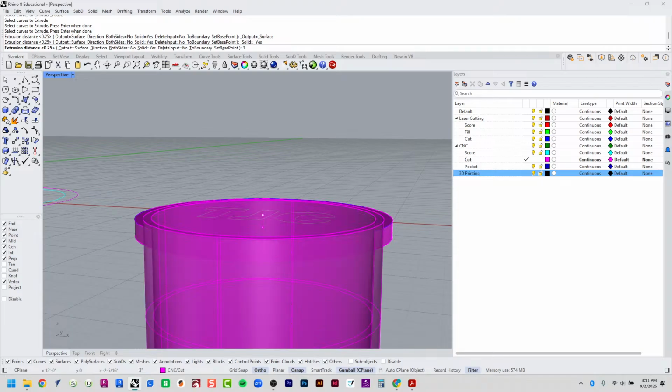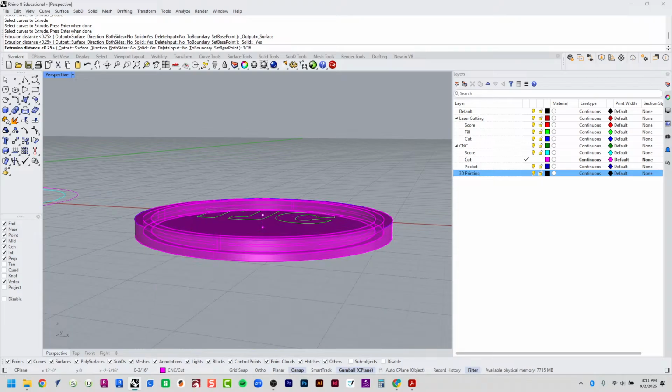So I'm going to type in 3/16. You can put a little quotation mark. Quotation mark means inches and imperial units. But you can also skip putting in quotation marks because our primary unit in this template is inches. So really 3/16 of a unit is 3/16 of an inch. Okay, so I'm going to type in 3/16. If you put in a quotation mark, that's fine. No biggie, it'll still take it. And I'm going to press enter.